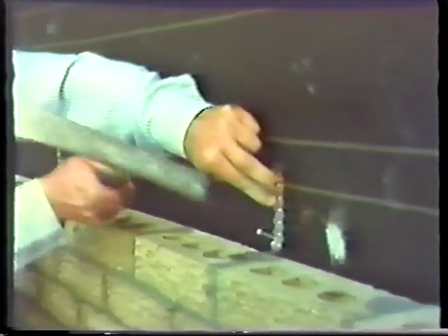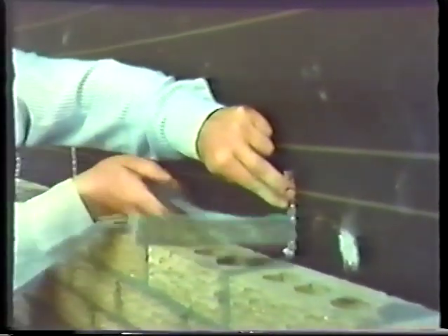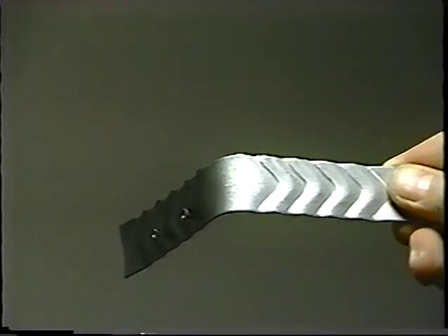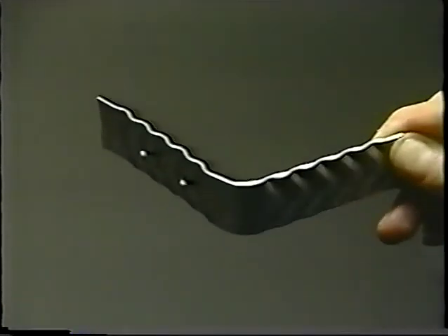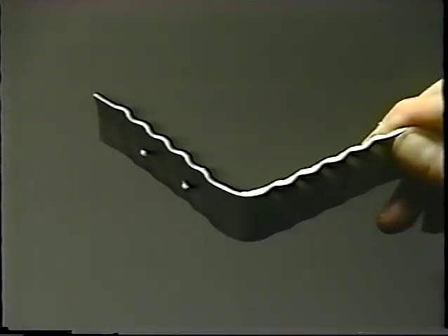All ties are required to have an adequate galvanized coating. The corrosion resistance of corrugated ties is usually poor. The galvanized coating is often cracked or knocked off when the tie is bent. If this happens, the corrugated tie may corrode very quickly. Therefore, ties which are pre-bent are preferred to those that must be bent in the field.